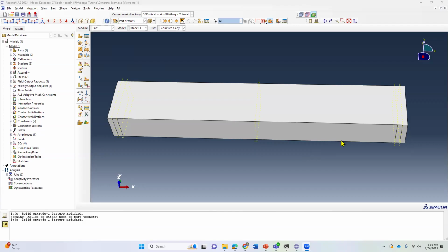For example, if I want to apply a half cylinder surface or half cylinder solid, or a rectangular solid plate here, then I'll have to define contact between my beam and the support. And contact is not good for convergence of a lot of analysis models.